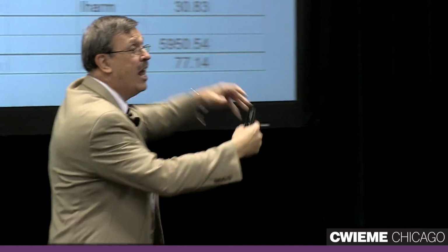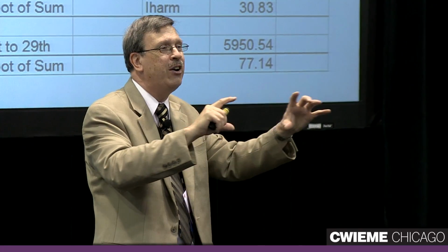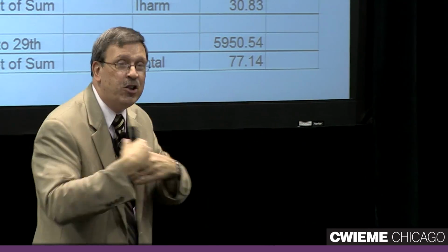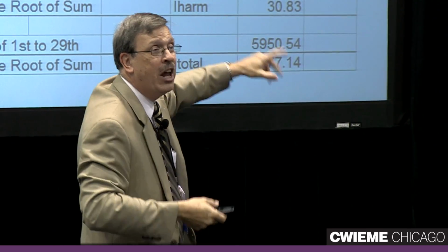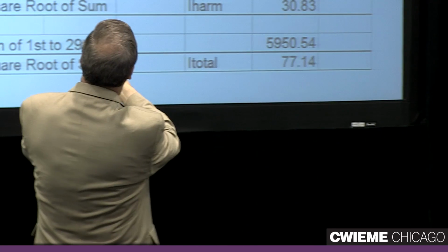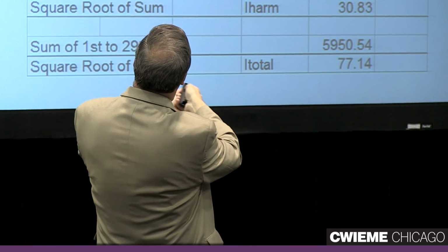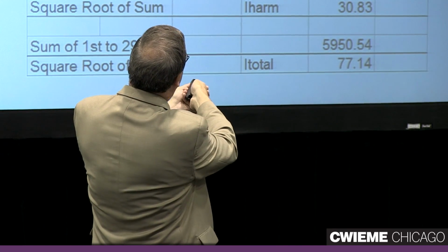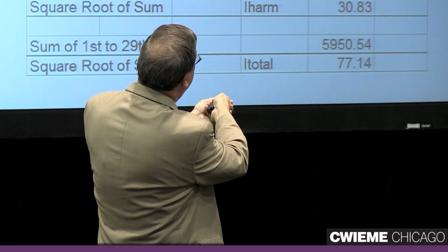But what it does is you put in that red waveform, you know, you type it in on those cards. Remember those cards? Some of you do. All right, good stuff. You type it in on that, and then you put that through the computer, and it comes out with a table like this, saying that red waveform is made up of a fundamental, which has this peak, this RMS, and 0 degrees. Third harmonic, there wasn't any third harmonics in there. There was a fifth harmonic with this amplitude, that phase angle, seventh harmonic with that amplitude, that phase angle.